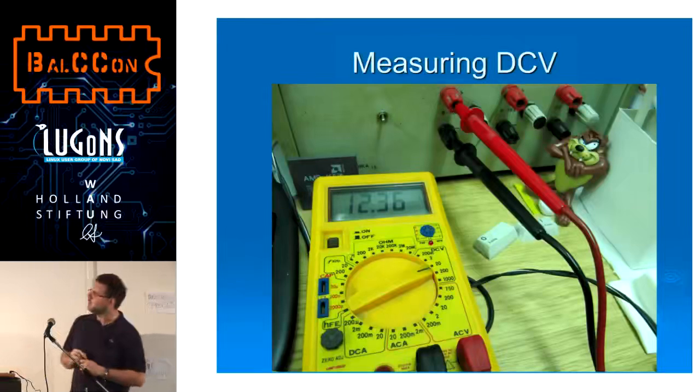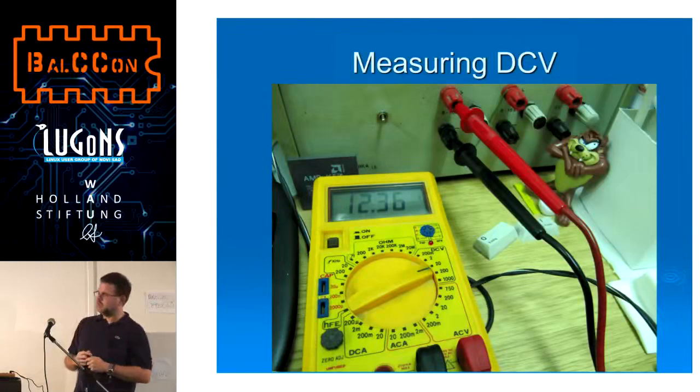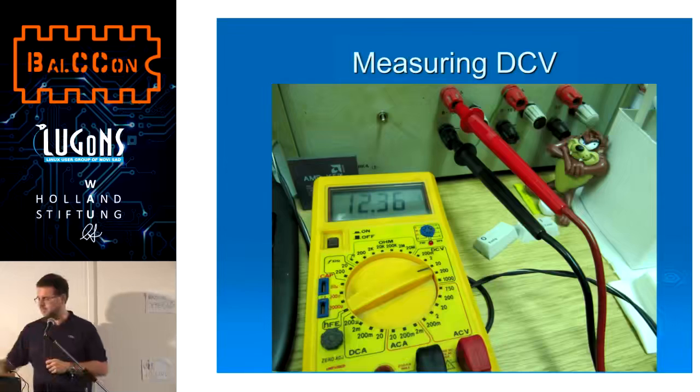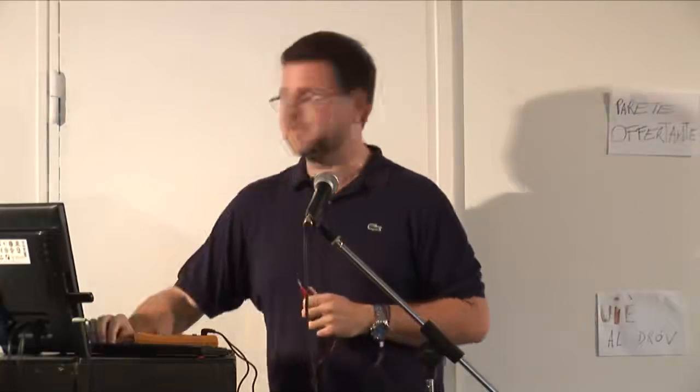This is the typical way to measure a voltage source. We have about 12 volts. And remember, always in parallel when measuring voltage.